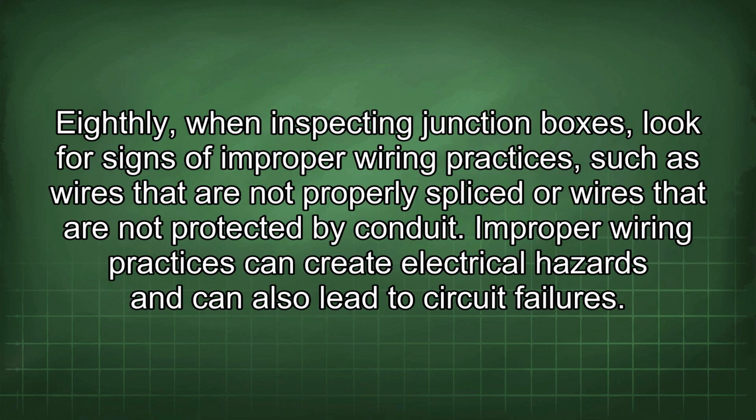Eighthly, when inspecting junction boxes, look for signs of improper wiring practices, such as wires that are not properly spliced or wires that are not protected by conduit. Improper wiring practices can create electrical hazards and can also lead to circuit failures.